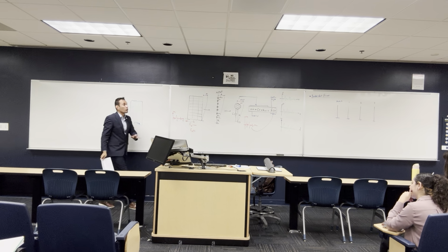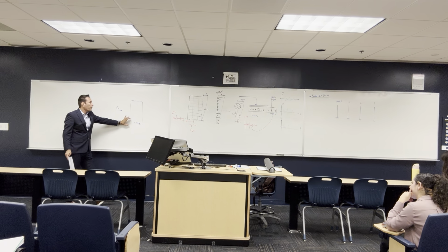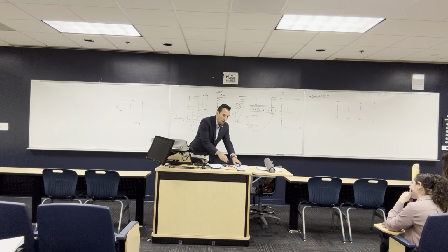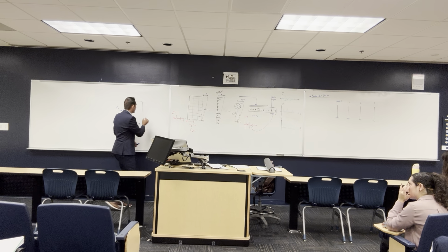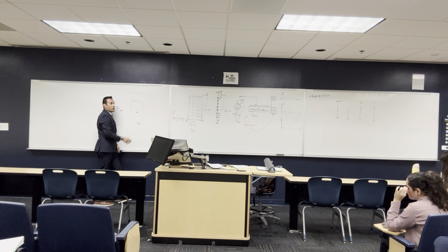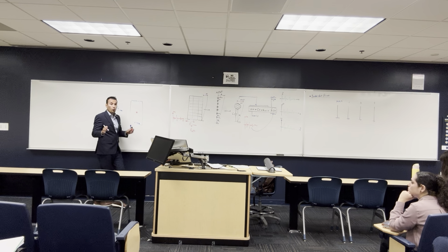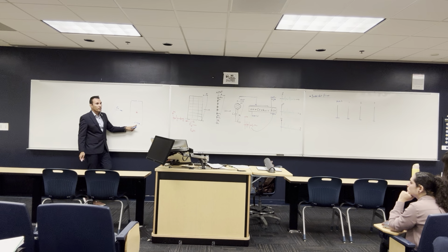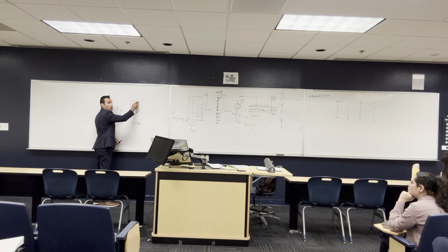So that's why, as structural engineers, we need to find out about something called the center of mass and the center of rigidity. The center of mass is always at the CG of the slab. Let's say the CG of the slab is here. That's the center of mass. The center of rigidity is where all the stiffnesses that contribute to the building are. Like this part is very stiff. If you have the shear wall here, I can imagine that the center of rigidity is the same as the center of mass, like here.